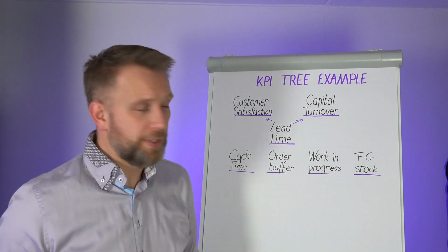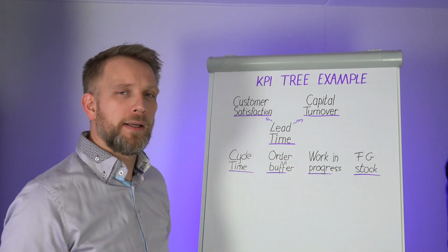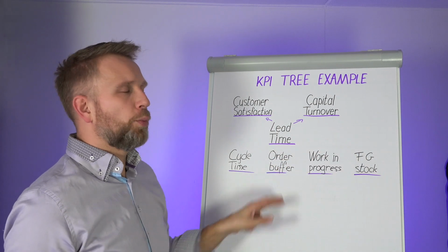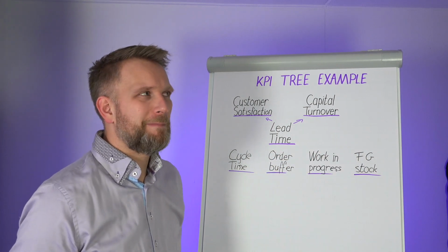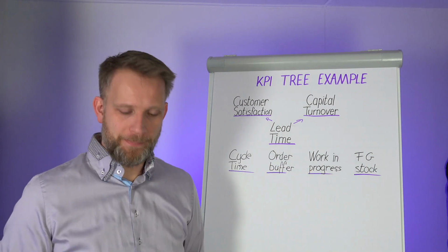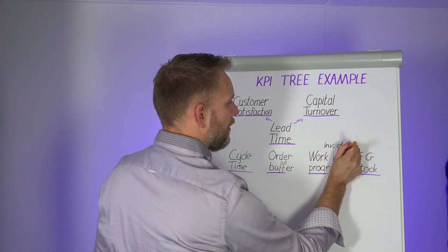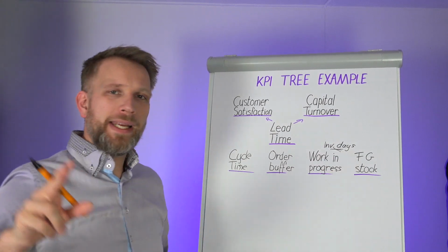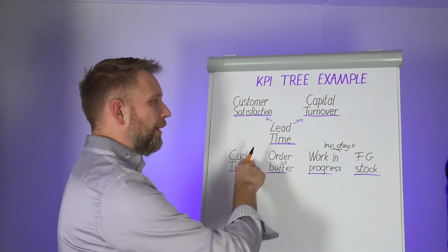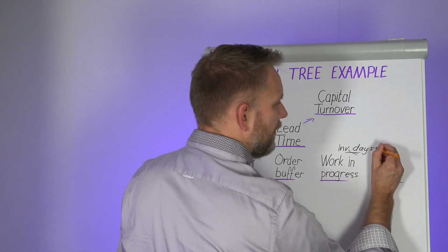These are inventories. So we have process time, but here we take the cycle time, and we have our waiting times. Now, what do we do, especially for these, is we don't really want to know the stock value or the number of items in stock. What we want to know is how many days, right? So this here is in inventory days. And inventory days, we use the takt time, or actually we use this cycle time to calculate. And so we have the number of items, and we multiply that by the cycle time.